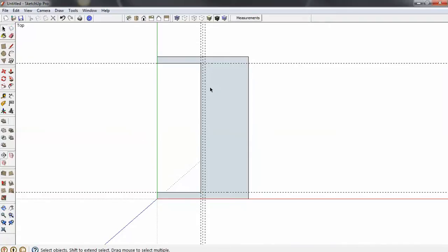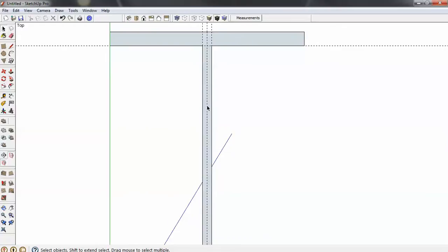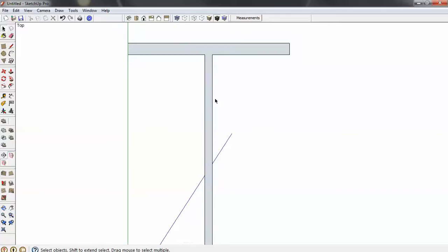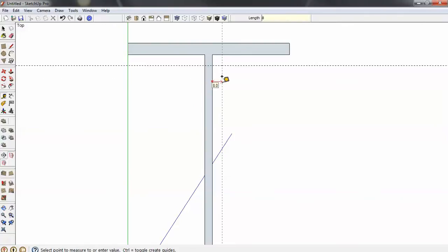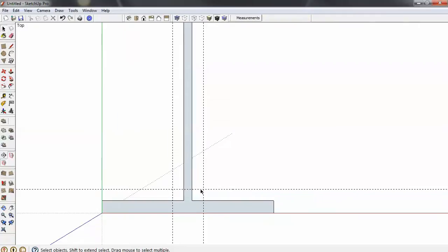Alright, I could just grab a couple of rectangles now and delete that out. Half a rectangle. Delete that out. Delete. And now my root radius was 8.9. I'll just get rid of those guidelines. T for tape measure. 8.9. And I'll do the same down here. 8.9. Alright, I've got the place to start my root radius.